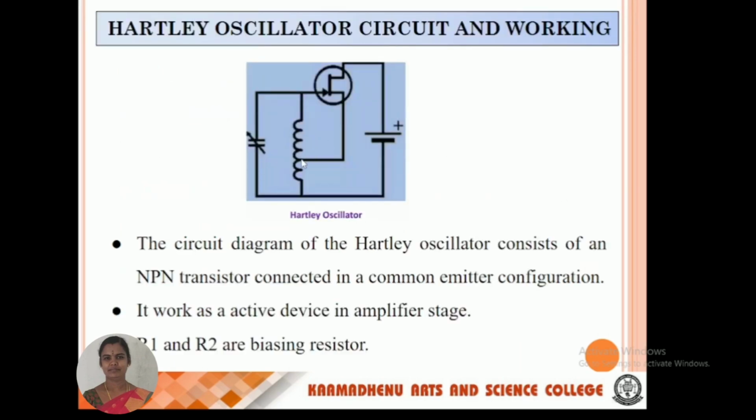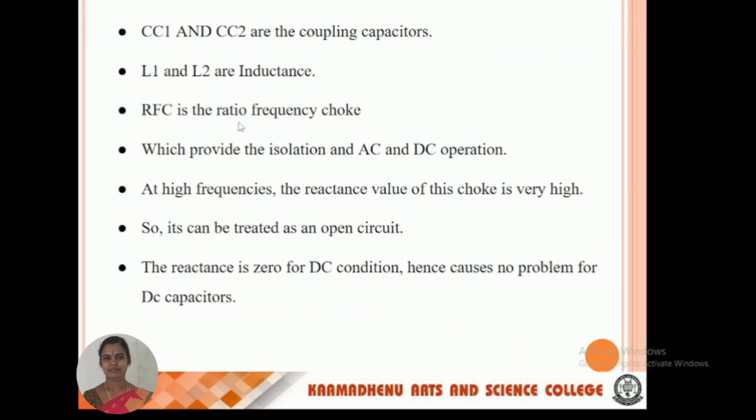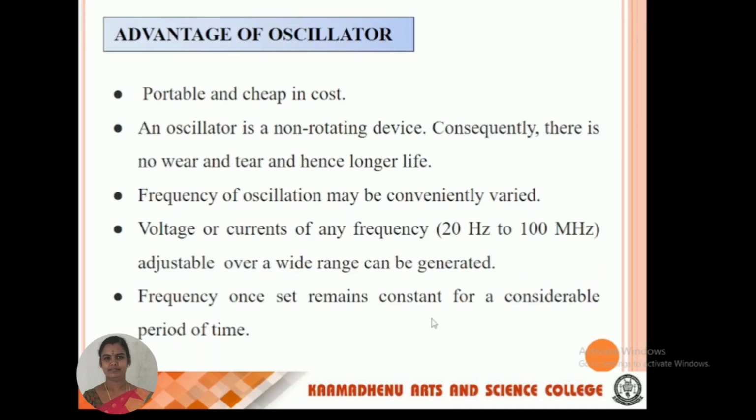These are all inductances. RFC is the radio frequency choke, which provides the isolation between AC and DC operation. At high frequencies, the reactance value of this choke is very high, so it can be treated as an open circuit. The reactance is 0 for DC condition, hence it causes no problem for DC.